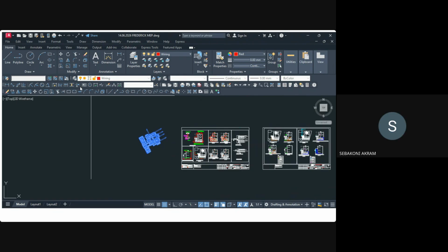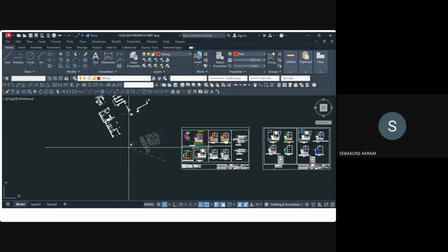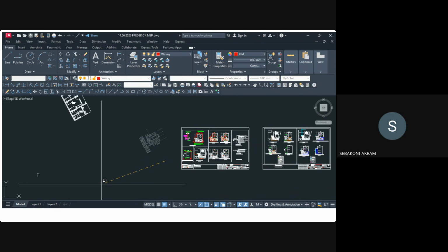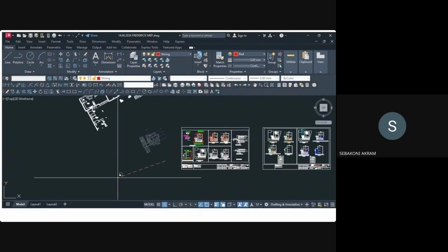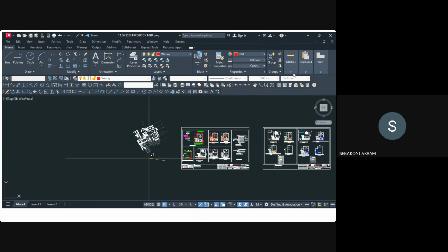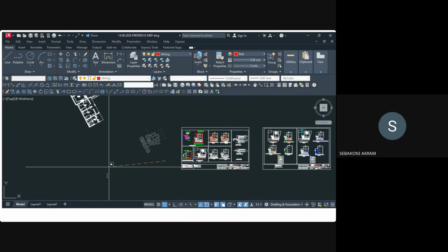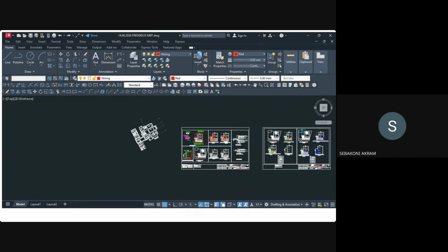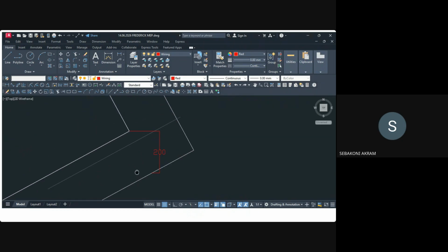Yeah, I've seen it. So I select a base point. Let me say I want to scale from here. I select my base point. Instead of just scaling freely, you come here because you are given options: specify the scale factor or reference. Are you together? So I come here because I copied this scaling factor. I paste it here, Control V, you know those shortcuts. Then I press enter. You would see that this is brought back to the original.